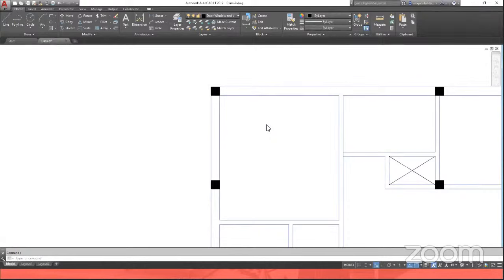Chaitanya, what exactly are you talking about? See, there is no shortcut which I was doing. I just selected the rectangle. I clicked on one point, and then instead of clicking randomly anywhere, I just gave it the dimensions. So 9 inches comma 9 inches. That's it, the rectangle has formed.